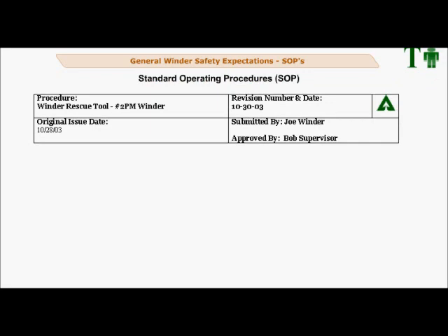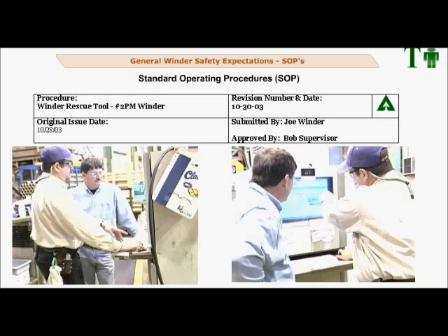SOPs. There shall be winder standard operating procedures and safe practices. Each mill shall have documented specific SOPs that ensure safe practices. All winder crew members shall be trained in and must follow the SOPs. All winder personnel must be able to access SOPs at any time.